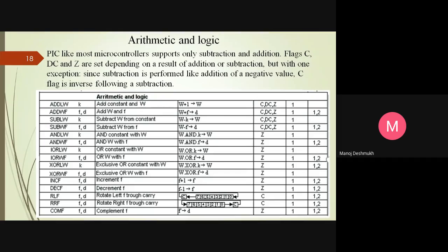But whenever we see, suppose, keyboard interfacing with the 8051, whether the key has been pressed or not, we see the carry status. So for checking the status of a particular bit, D7, D4, D3, whatever it is, in that case you should always work with the 8 bits only.